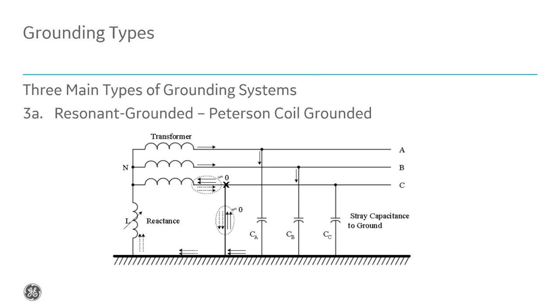It has no effect in the case of arcing cable faults. The cables can produce repetitive and harmful strikes, so when we're talking about underground, tuning is an issue, right? Because tuning that reactance to the power system can be very difficult.